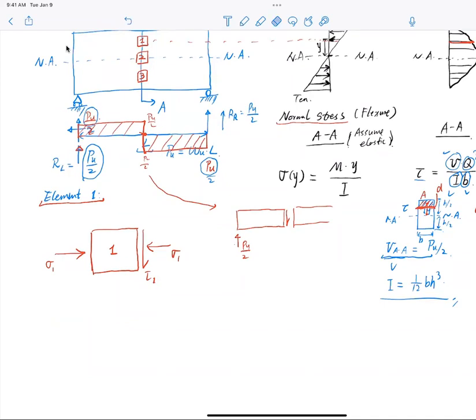So I require all my shear stresses to have the same sign, arrow against arrow, tail against tail, and everywhere it is tau 1. Same magnitude everywhere, so that I will not result in a spinning moment with respect to the centroid of this element.